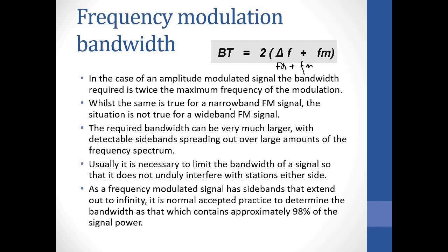Whilst the same is true for narrowband FM, the situation is not true for wideband. So for narrowband FM, the bandwidth is almost equal to that of an AM wave. For wideband, the required bandwidth can be very much larger, with the detectable side frequencies spreading out over a large amount of the frequency spectrum.